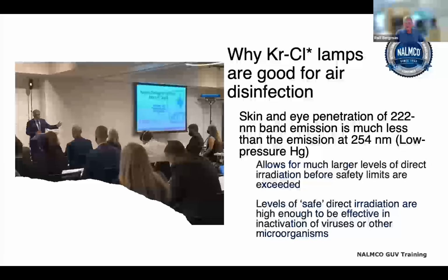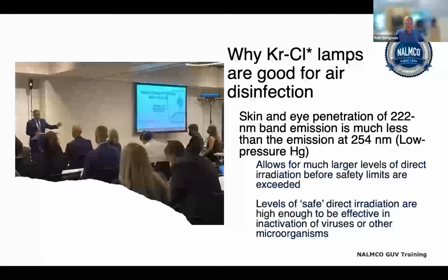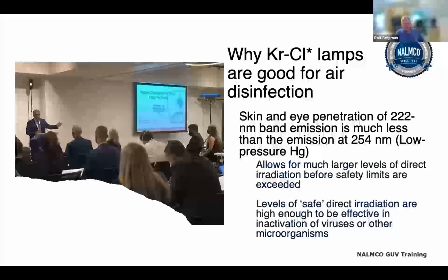The excimer lamps, particularly krypton chloride, have an advantage in air disinfection because the skin penetration at 222 nanometers is significantly less than that of 254.